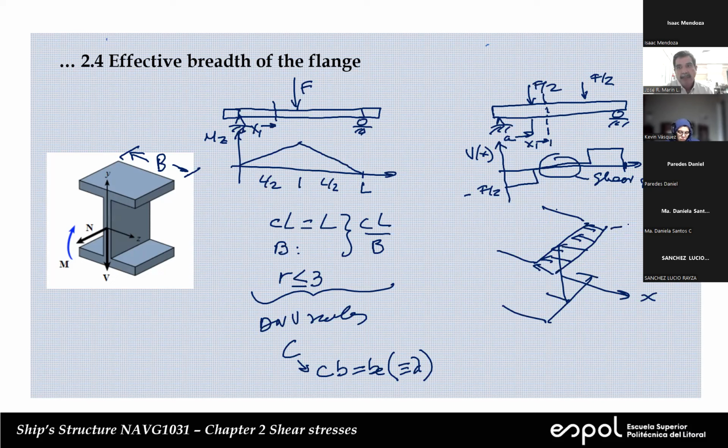So it's going to be minus Mz y over Iz. So in this case, the values of the strains should be close. Remember, this is experimental, so we can never expect to follow exactly the theory. So it's going to be close. That's enough. So that's going to be a good way to check these results.